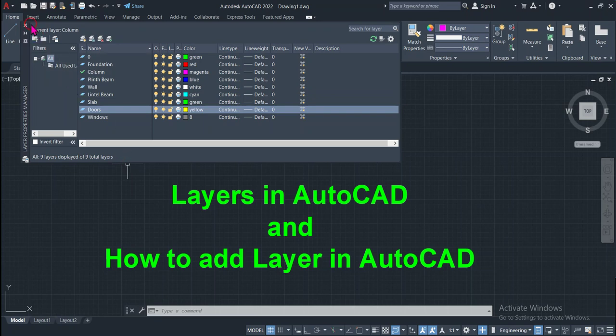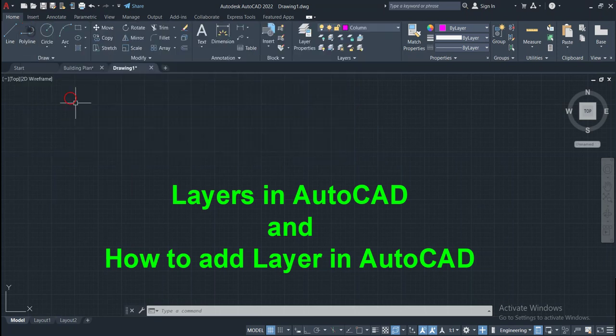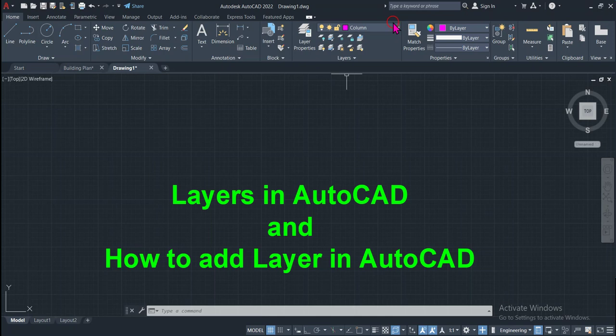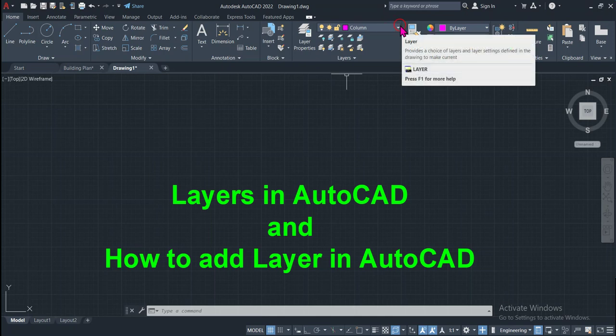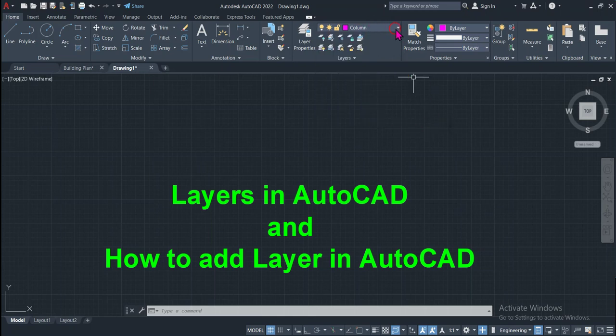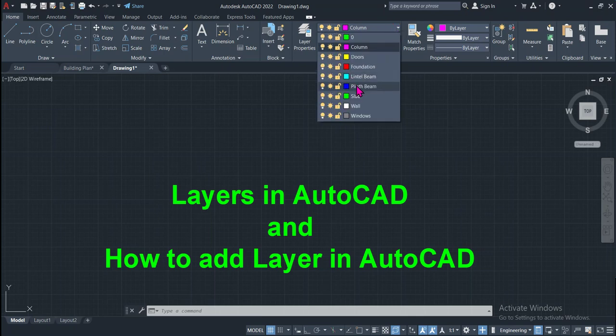So then you can close the layer window from here, and now you can check the layers that you have added by clicking on this drop down button. Before adding the layers there was only one layer. Now you can check that there are different layers that we have added just now, and the column layer is now active. You can change to the beam.